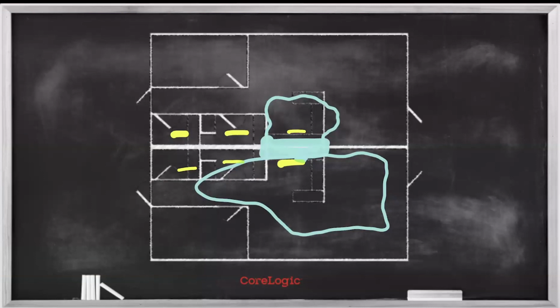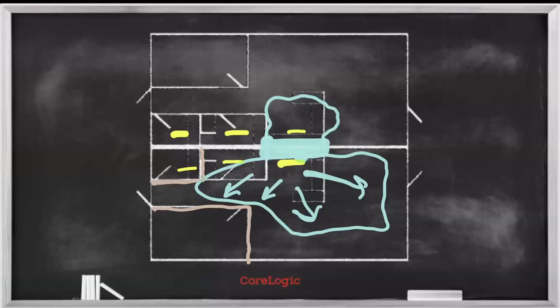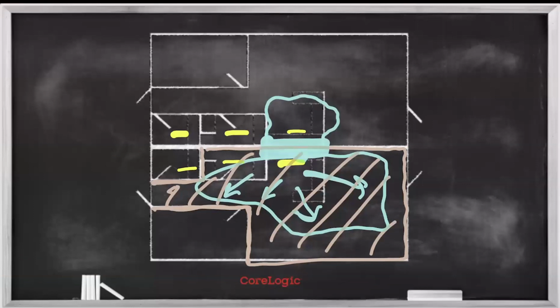Now, having said that, let's talk a little bit about classification and how I would apply class. In this lower area here, where I've got a much larger portion of my structure actually impacted or affected by water migration, here we're dealing with a much larger overall surface area that is impacted. If I close this room off because it's not affected, and I close this room off because it's not affected, to apply my class of water, I'm going to consider the amount of this area here, and I'll shade this in to be clear, what amount of this area has been impacted as a general, approximate percentage.